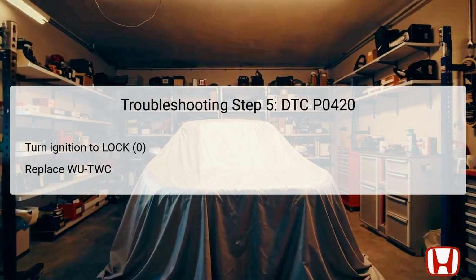For the 5th step, turn the ignition switch to the lock position to ensure that all systems are properly shut down before making any replacements. The next action involves replacing the warm-up 3-way catalyst, WTWC, an integral component in managing emissions and providing a cleaner exhaust stream.